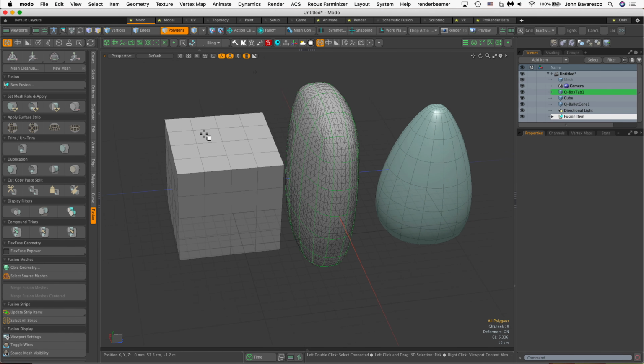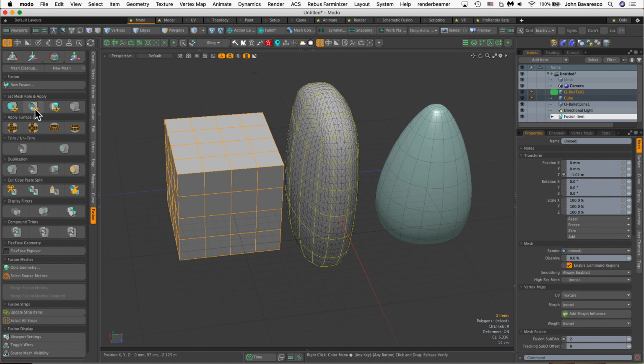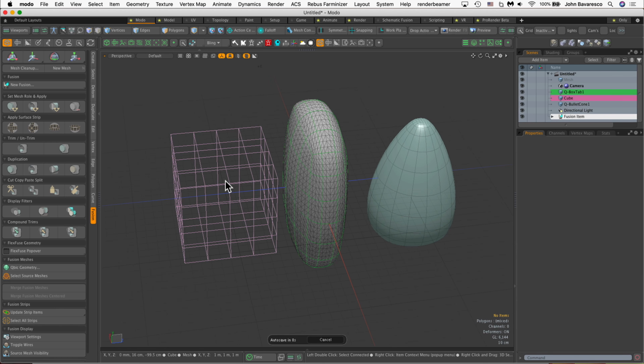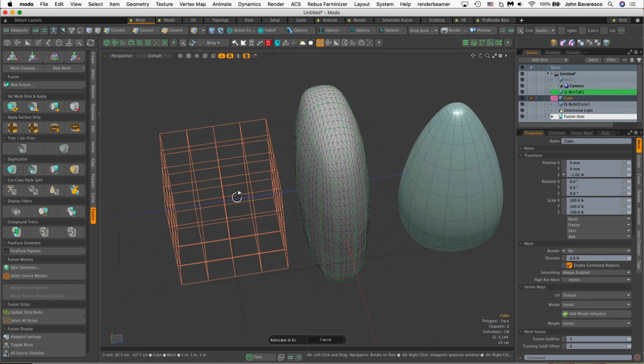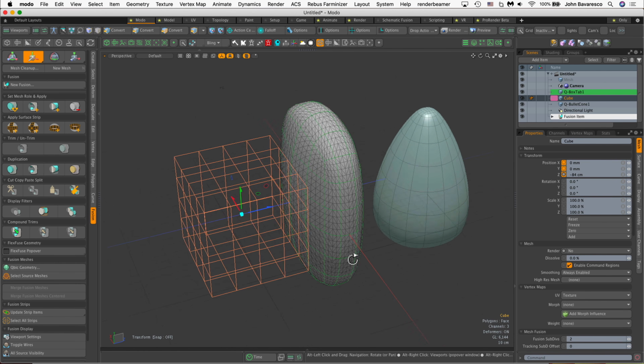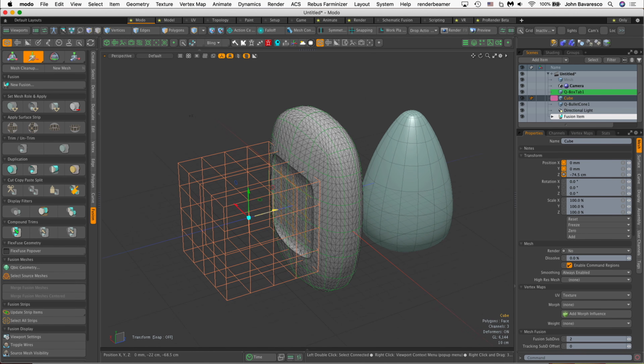So I'm going to make this guy a subtractive element. All I have to do is in component mode, select that, and go click there for subtract, and that made that a subtractive element. Now I'm going to intersect that object with my primary, and hit the W key, and let me swing around here so we can see this a little bit better, and watch what happens.